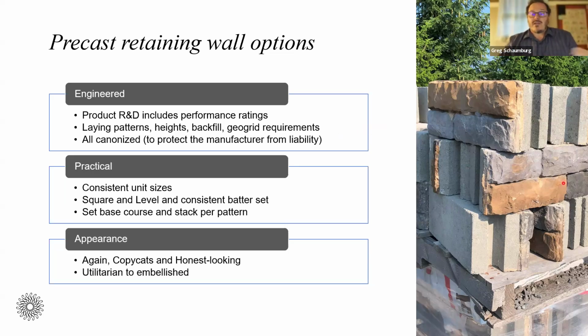You can certainly build a 6-foot retaining wall, but you would be required to use a segmental wall engineer, which they weren't willing to do. And you'd also want a railing, and you'd also want to build it with a different material that's rated for building that 6-foot wall. So everything's possible, but in this case, the reality and the physics weren't lining up. So we just said, let's part ways and figure something else out.